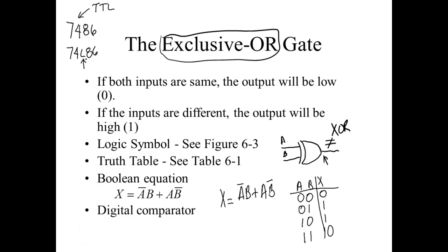That makes sense? So it'd be like buying a car. Then you have options, and that would be where your L and your LS and your H series and your HCTs and all those come into play, the options of the car. You pick one and hold it up in your hand, it's a 14-pin DIP, they all look exactly the same. And the pinout would be what? The same.